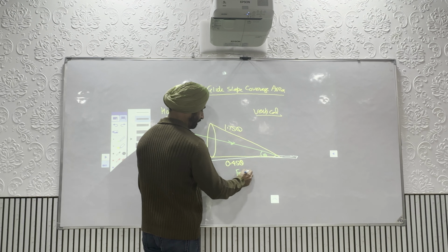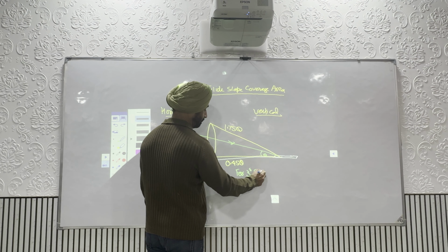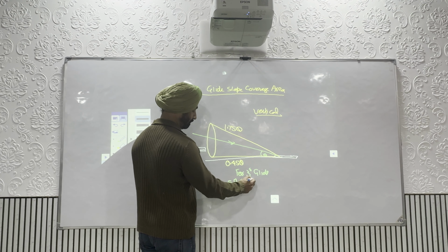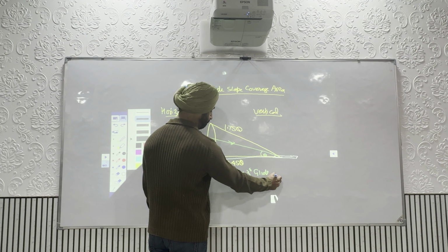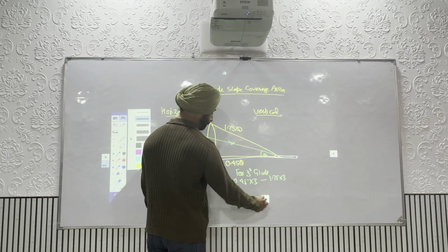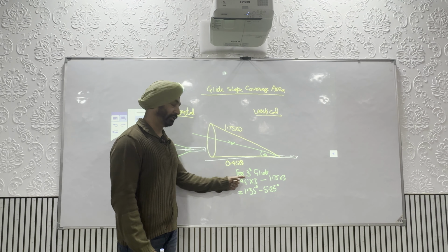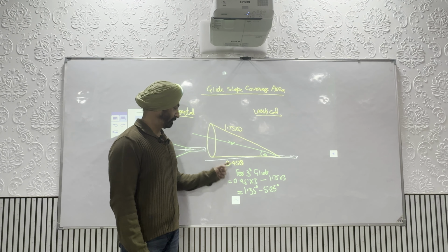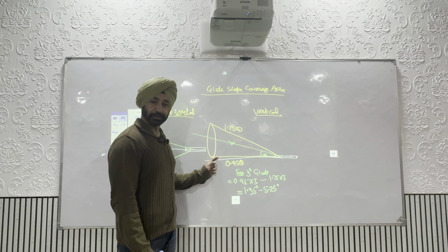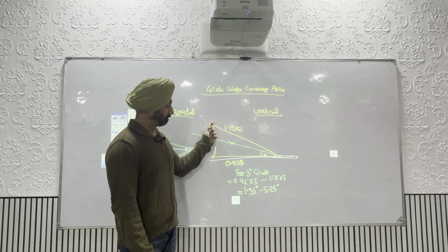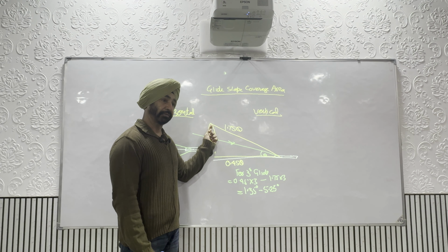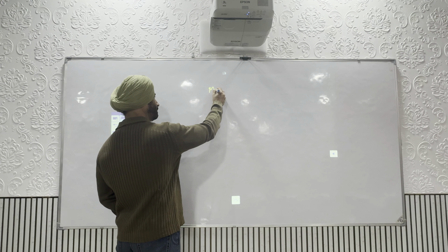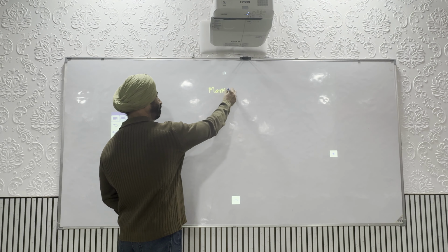For a 3 degree glide slope, 0.45 into 3 to 1.75 into 3. So for a 3 degree glide slope, the signal can be received from 1.35 degrees to 5.25 degrees above. And the third component is the marker beacon.